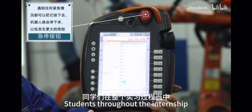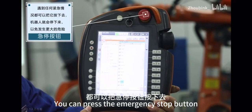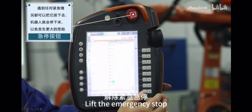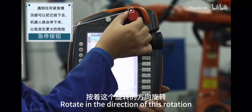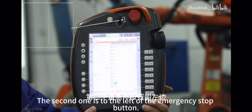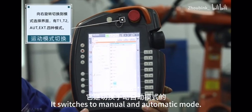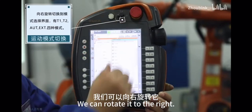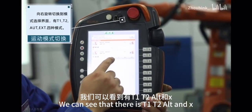Students, throughout the internship, in case of an emergency, you can press the emergency stop button. When you press it directly, it will go down. To lift the emergency stop, rotate it in the direction of the rotation arrow, and it lifts. The second one is to the left of the emergency stop button. It's a black key that switches between manual and automatic mode. We can rotate it to the right, and it will enter another interface. We can see that there is T1, T2, Auto and External.